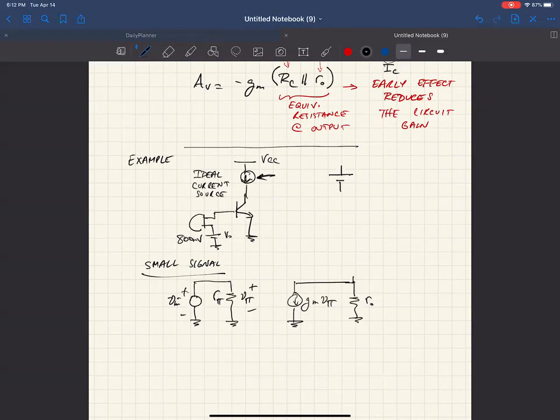So in the case of a voltage source or battery, this turns into a 0 volt battery, because the DC voltage you zero out, which looks like a short. Now in the case of a current source, we do the same thing, so we zero out the current of the current source. Now if you took a current source and zeroed the current, you end up with an open circuit.